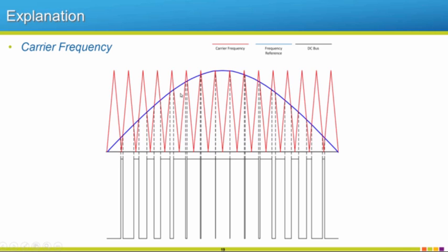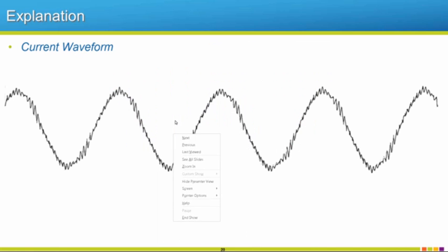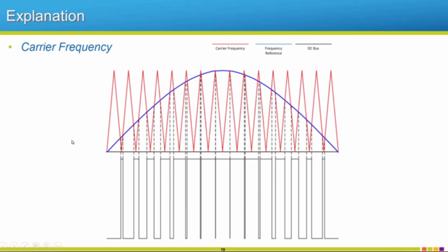So if this is 60 hertz, so how we vary the frequency, this wave that we're trying to make is just going to get squished or wider. So, you know, the more squished it is, the faster our motor's going to turn. So, you know, if you're running some high-speed machine, this could be, you know, 400 hertz or more could be possible. And maybe you're wanting to run at low speed. As long as your motor's capable of running at this low speed, you could be running with a very, very wide or long stretched out part of your wave.